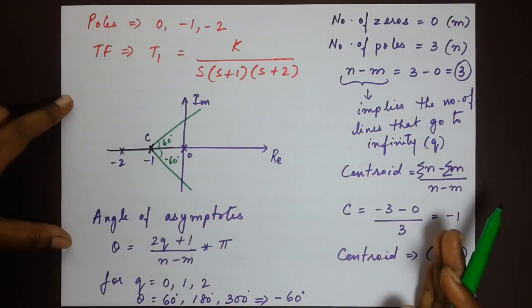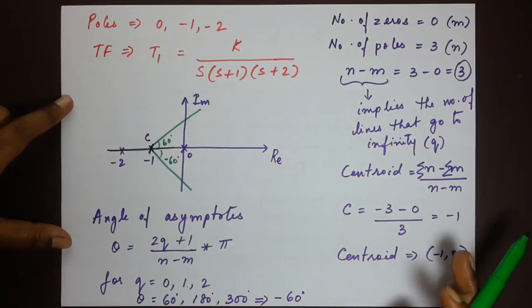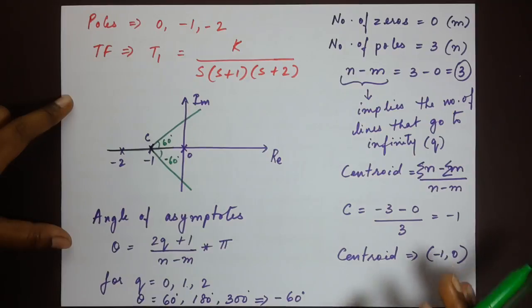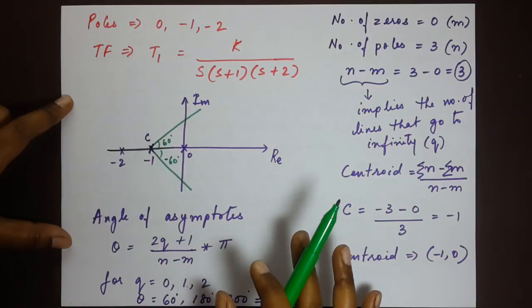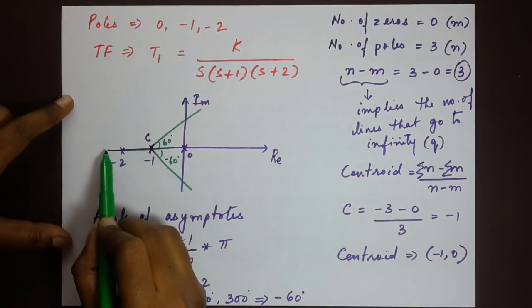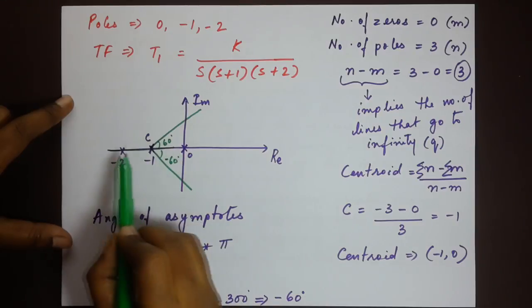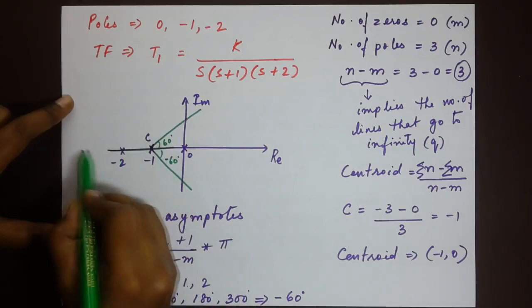How many poles or zeros you find on the right, the sum of those, if they are odd number of zeros and poles, that part of the root locus is present in the plot. Okay, so let's note here. If I take minus 3 point, count how many poles and zeros are there here. 1, 2, 3. 3 is an odd number, therefore this portion here exists in the root locus.